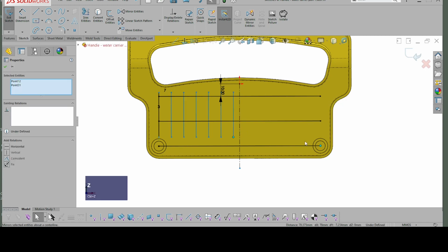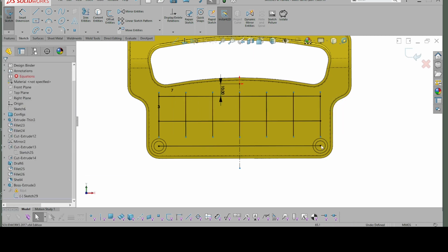So that was not so good. Put those 2 in and make them vertical. There we go. Okay, so if I made it coincident, it would come down to this point, link to this point, which is not what I want. So let's see what happens here. I can tell you now that the rib for that line is going to only extend to that point. The rib for that point will only extend to that point, but these ribs will extend beyond that. And these horizontal ribs will only extend to the vertical ends, and then they will cross through that point there. Let's see if I'm right.